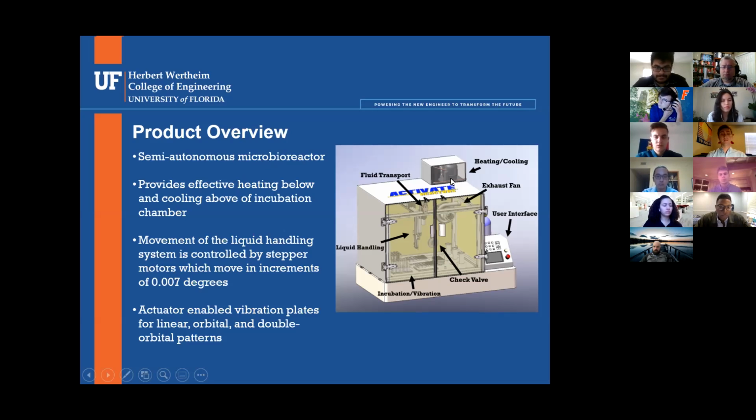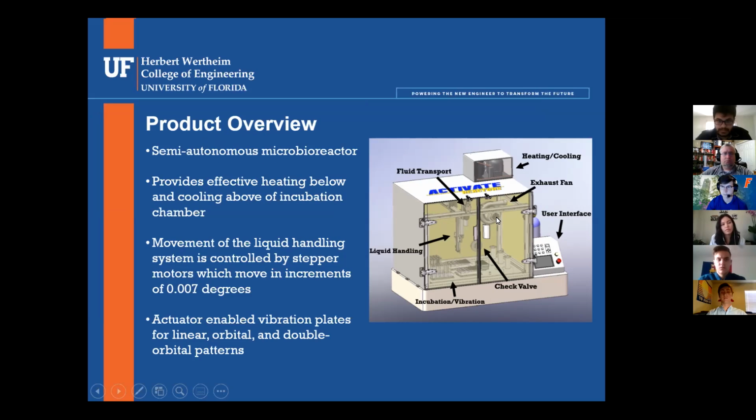A gas mixture from the tank located on the right-hand side of the design will be injected into the main enclosure to culture the specimens. But before this happens, an exhaust turbine takes out ambient air in order to get a controlled atmosphere inside the reactor. Since we're injecting possibly a large amount of gas into our sealed volume, we've installed a check valve which can mechanically regulate the maximum pressure inside.